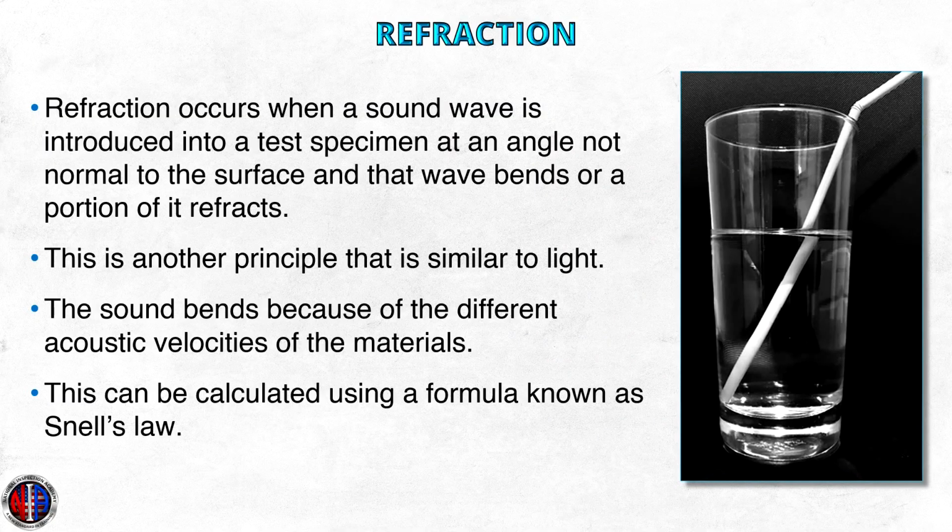Refraction. Another principle of sound is refraction. Refraction occurs when a sound wave is introduced into a test specimen at an angle not normal to the surface, and that wave bends, or a portion of it refracts. This is another principle that is similar to light. If looking at a straw through a medium like water, it would appear as though the straw were bent. This refraction occurs because of the different refractive indexes of air and water. In ultrasonic terms, the sound bends because of the different acoustic velocities of the materials.